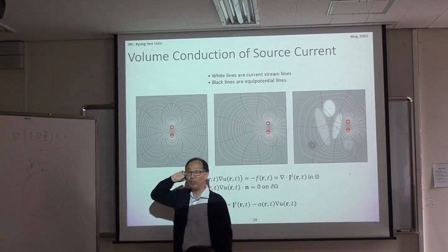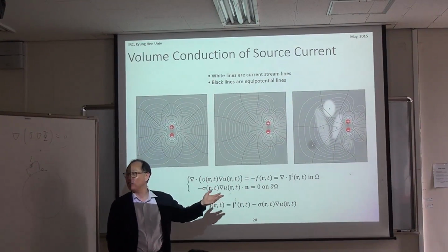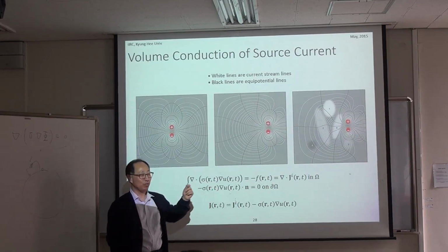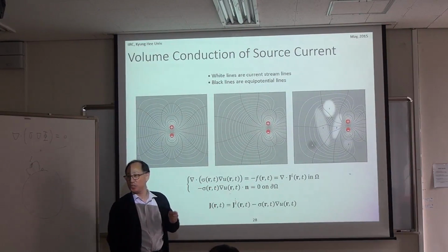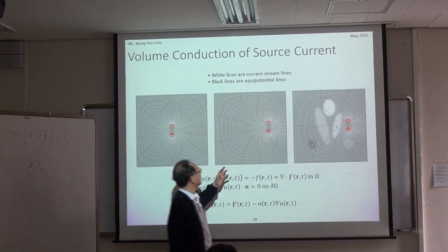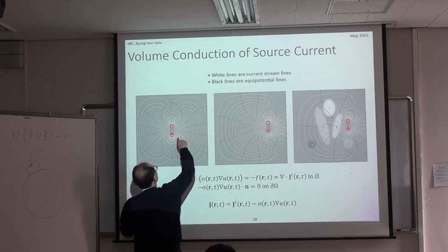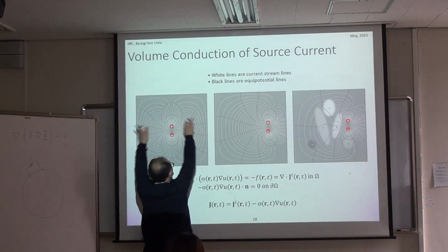And what's going to be the boundary condition for this case? Outside the domain is just the air, an insulator. So we have to use Neumann boundary condition, which means Neumann data is 0 everywhere. Then we can easily find the current flow this way.